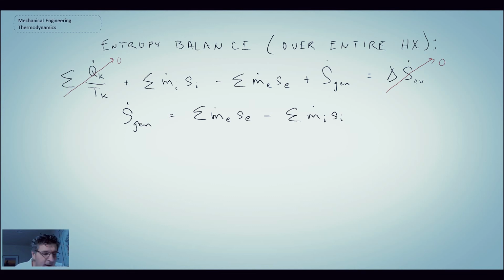So the fluid exiting, what we can do is look at the change of the mass flow rate, and what we'll do is we'll take this on the glycol stream and the water stream, each of them by themselves. And these are little s's that I'm writing here in the rate form equation. It's a big S on the left-hand side of the equation and little s's on the right-hand side.